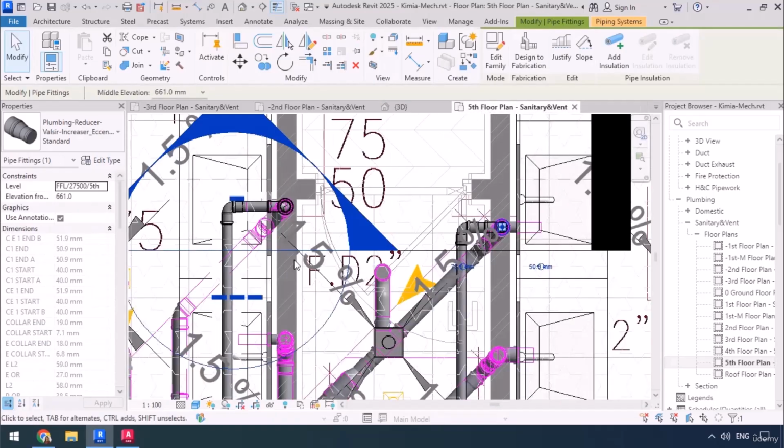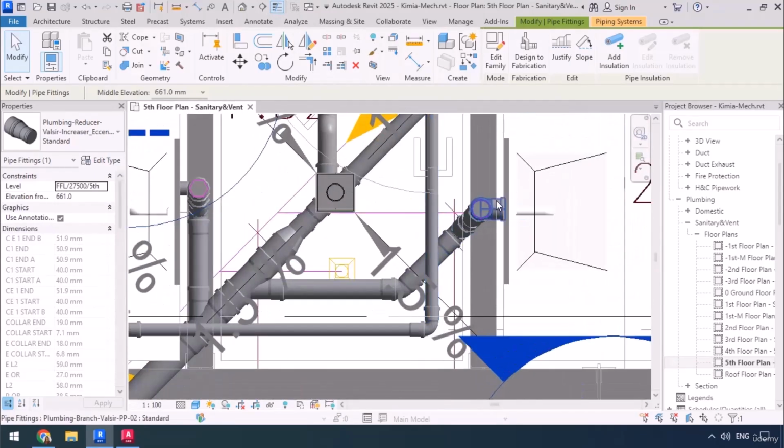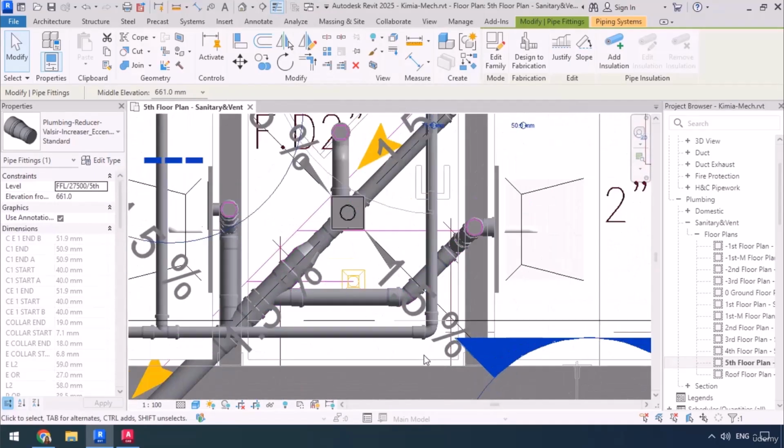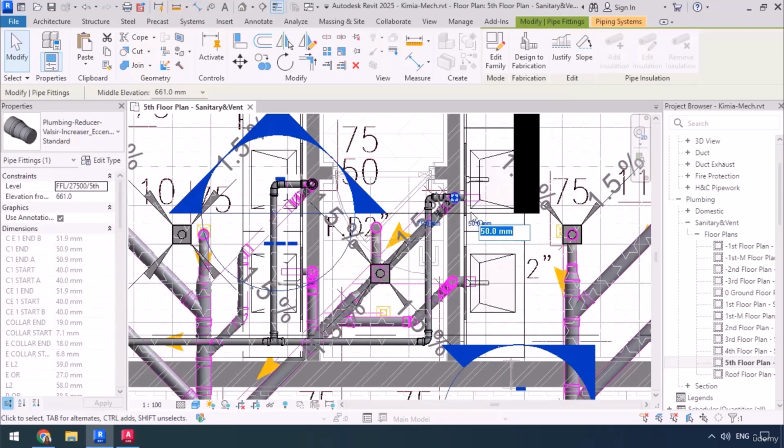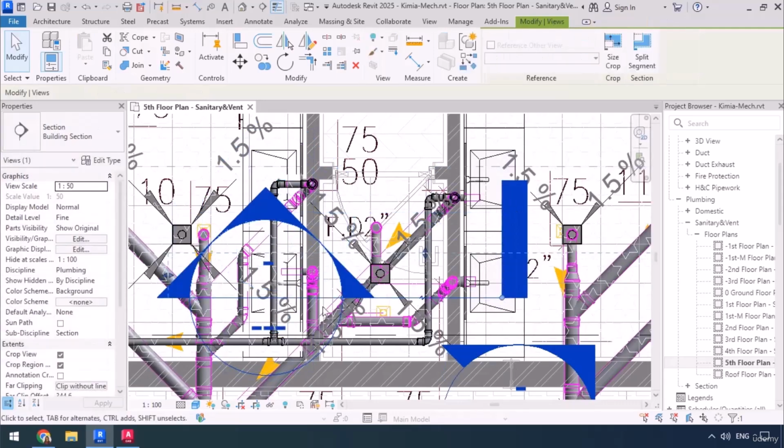Now let's head back to the floor plan. And then I'm going to click on this close inactive views to close the extra views. And now I'm going to be connecting this pipe to this lavatory the same way as we have done so far, so I'm going to have to move this section onto it first. I'm going to also stretch it because we're going to want to see both pipes and connect them together.